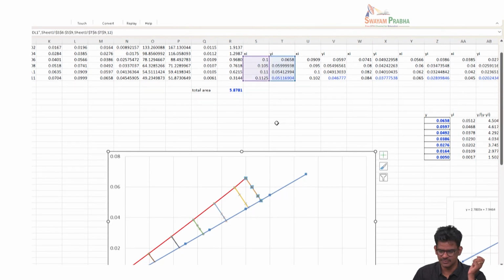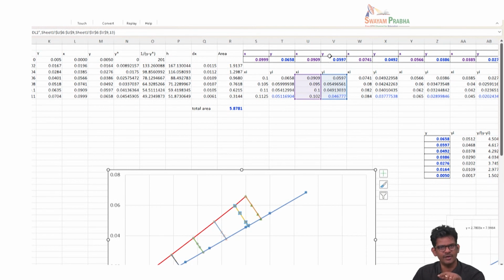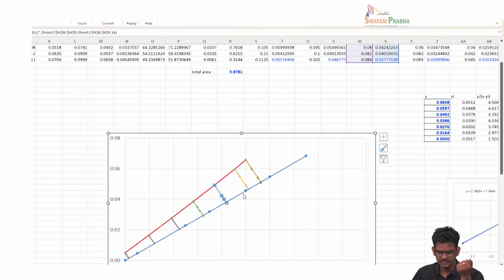and that would be one of these lines here. So you can see this line starts from an xy on the operating line to the terminal point. Then this line is based on another point on the operating line, starting from here, since I know the slope Fl by Fg, and this orange line is obtained. And this line is based on the xy combinations on the operating line here, and then the corresponding driving force line. So you can continue this. Here I have shown some 7 lines, but you can actually make an infinite number of lines. I just did 7 because I need only 7 or 8 points, but you can do as many as you want.